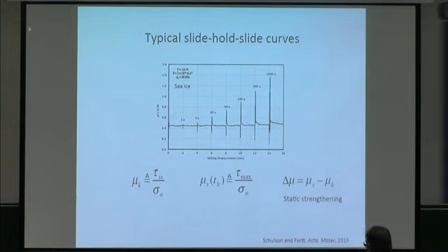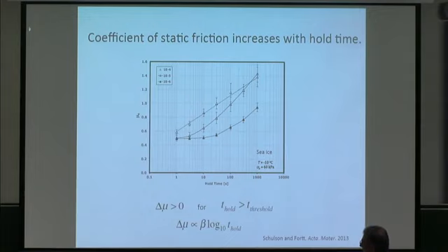We're not the first to see that. That was seen by Leishman and others before us, and I'll show you their results. Let's describe that coefficient of friction in terms of the shear stress divided by the normal stress acting across the sliding plane, in the way people generally describe friction. And there's a characteristic behavior.